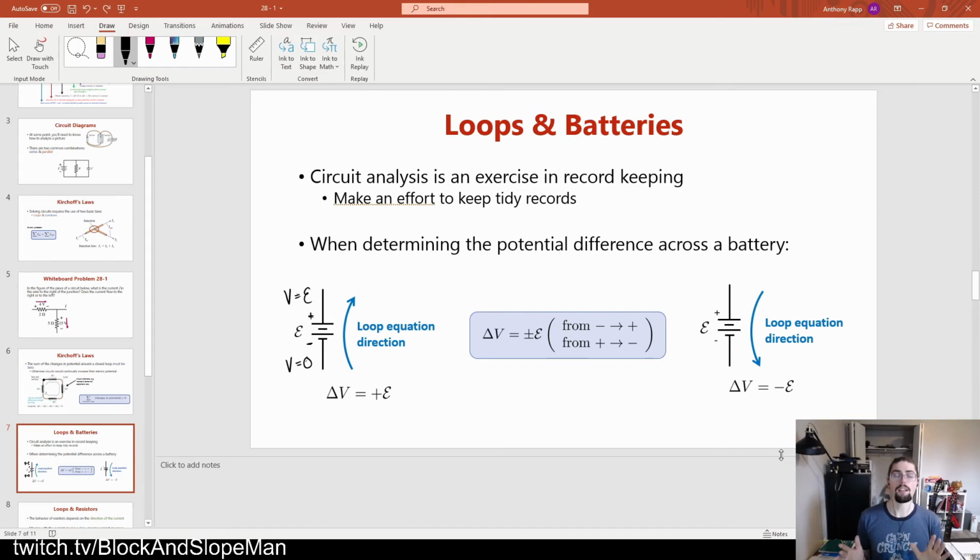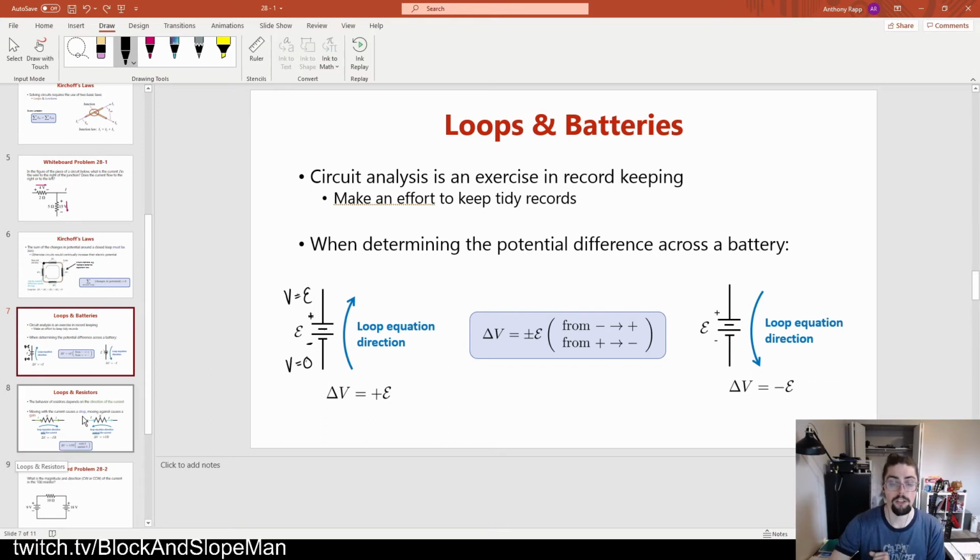But even if I stack a ton of those, it wouldn't do anything until I complete the circuit somewhere else. Right? I can stack together as many batteries as I want, and in fact, that's what a 9-volt is. It's 6 1.5-volt cells, but it doesn't move any charge until I have something connected to those 2 ends. Then I close the circuit, then current's allowed to flow through. So, that's how batteries contribute potential.